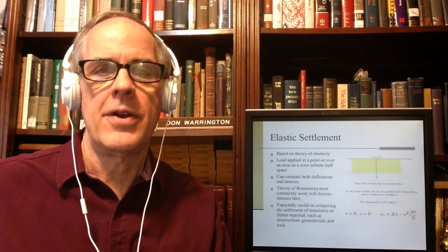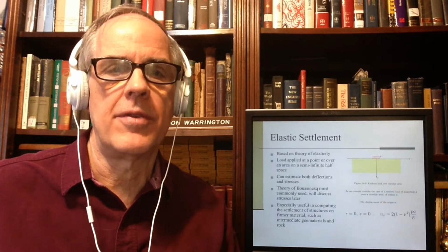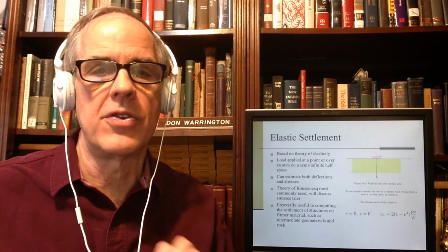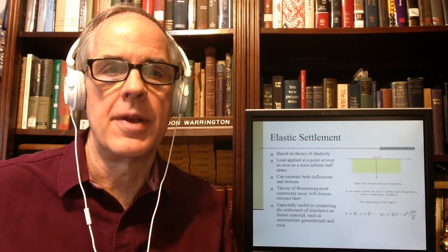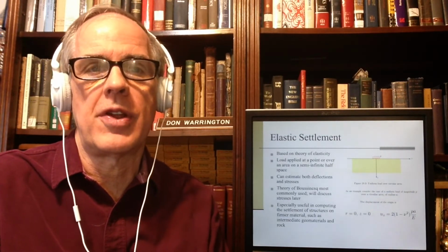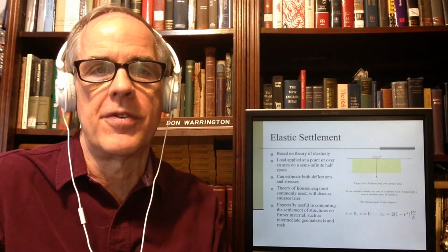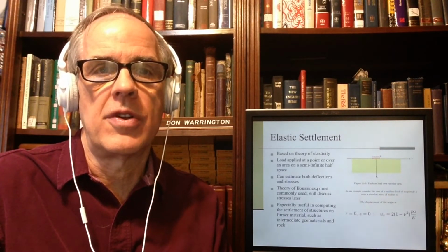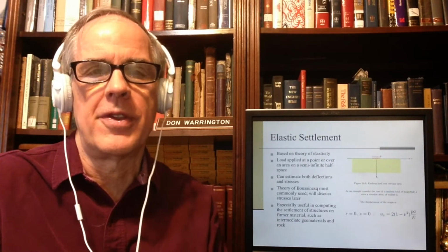Well, there have been different ways of teaching this over the years in terms of elastic settlement. The classic way of doing it is that you would use the elastic settlement for the first stage of deflection and then use consolidation and other types of settlement for the next two.